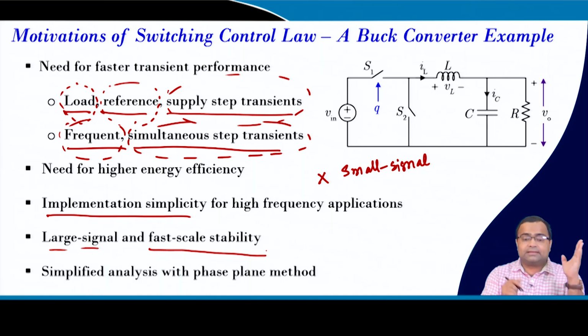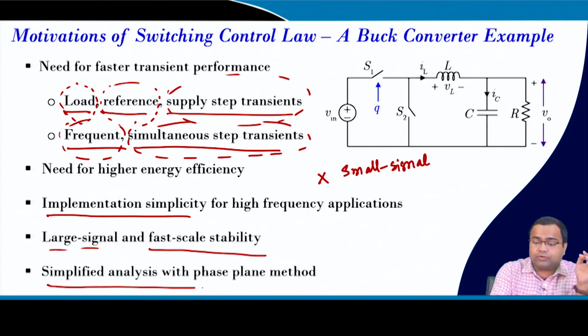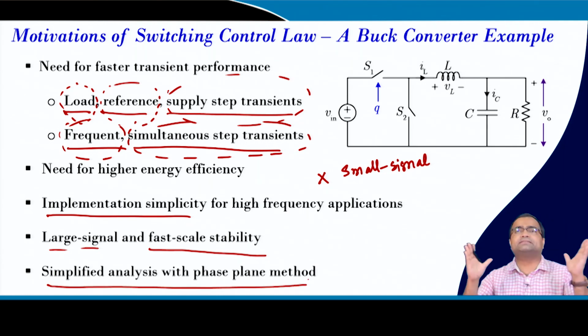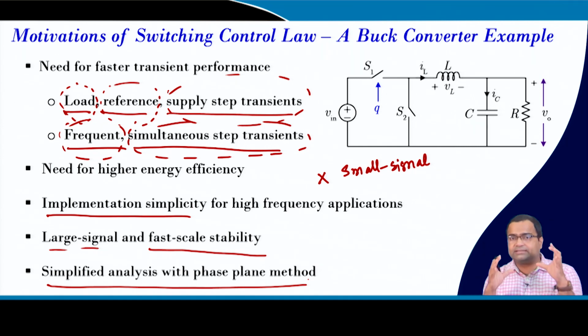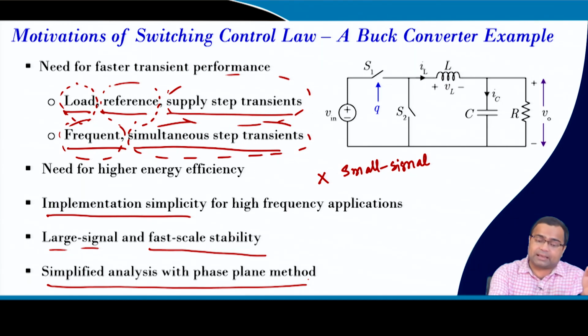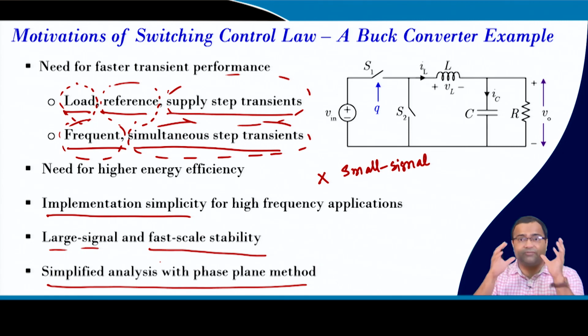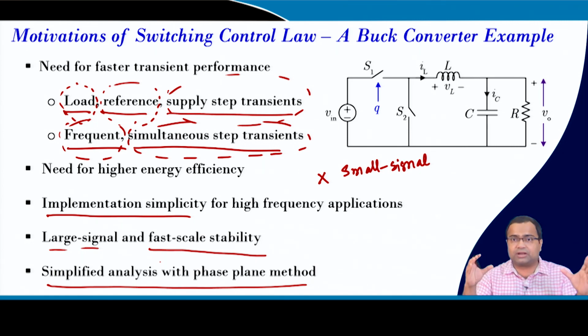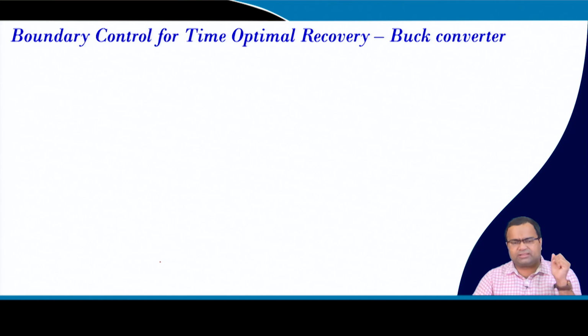And finally, our analysis with the phase plane should be very simple, so that we can visualize how the trajectory moves and how we can link this trajectory to our control law, as well as link some of this switching logic with our conventional PID controller, which we traditionally use and which is very well known. So these are the objectives in today's lecture. We will start with the boundary control for time optimal recovery.